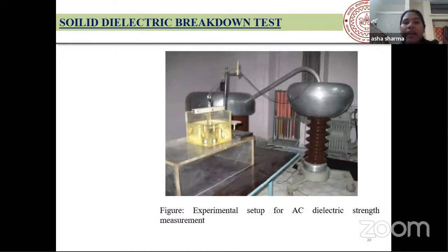Next is the solid dielectric breakdown test. This test we have carried out in our own lab. This is the high voltage transformer, this is our coupling capacitor, and we have used the solid breakdown sample within transformer oil. As I explained in the earlier slide, if I don't use the transformer oil, there is a possibility of air breakdown instead of solid dielectric breakdown. That's why we immerse the solid sample in the transformer oil.